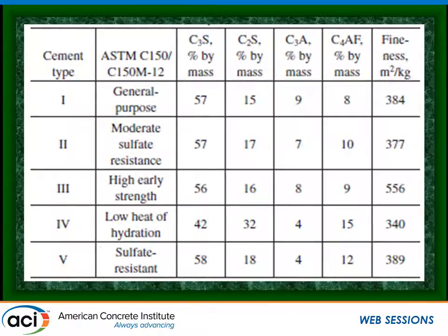There's 5 major types of cement. The Portland cement, ASTM C150: type 1 for general purpose, 2 for sulfate resistance, 3 for high early, 4 for low heat, and 5 for high sulfate resistance. There's also another 3 where these same types are combined with an air entraining material so they can be sold as an air entraining cement. This was the common way of making freeze-thaw concrete, was using air entrained cement. Nowadays that's much more often taken care of by chemical admixtures, and there's very little of the air entraining cement made, but it is still made.